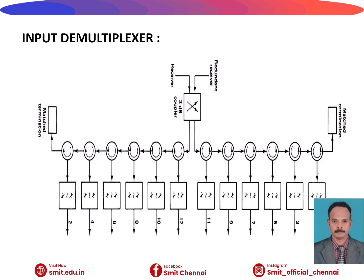Then coming on to the working of TWTA, it will have an electron gun that will generate the beam. That electron beam will travel along the RF slow-wave structure, and the energy transfers from the electrons to the RF signal. Then the RF signal emerges with greater power. So the advantages are high gain, high output power, high frequency capability. These are the important aspects of TWTA.